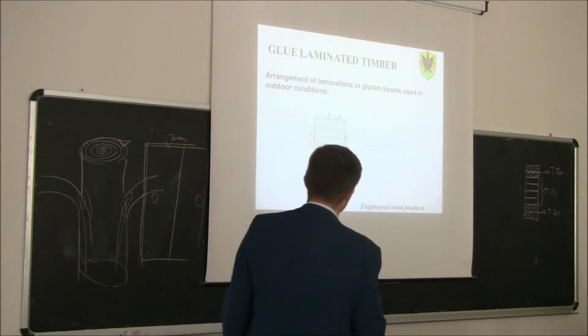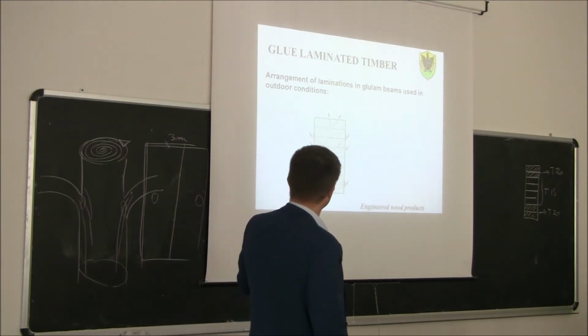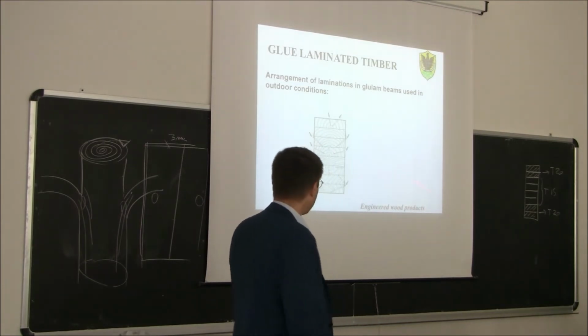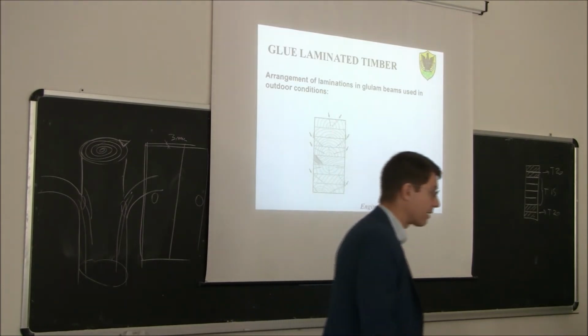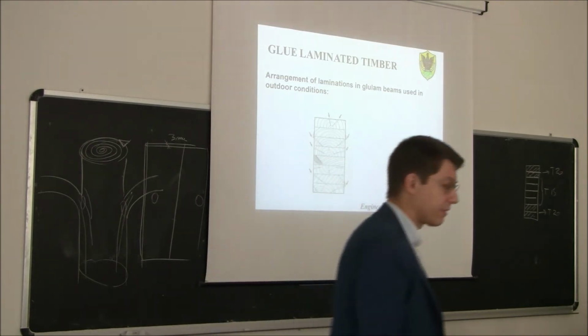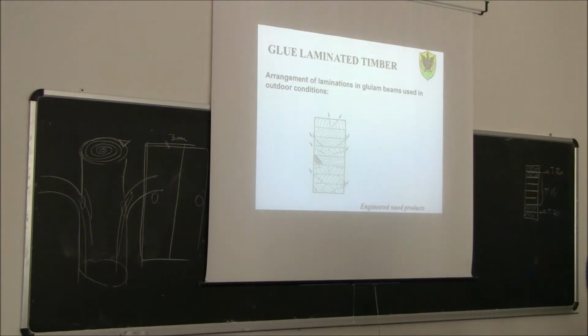Okay, one important thing: often during the drying process you get some cracks in the planks. So it's very important that those cracks are oriented in such a way that, if you have to use the glulam in outdoor conditions, the water doesn't penetrate inside.